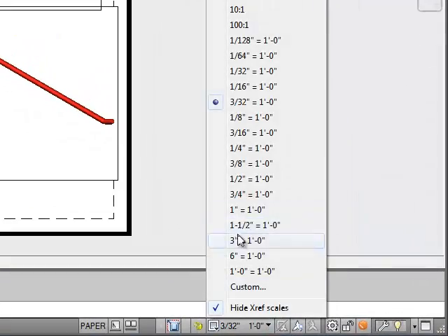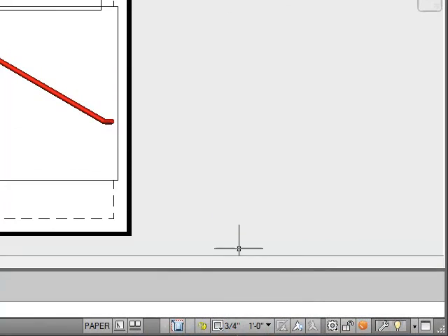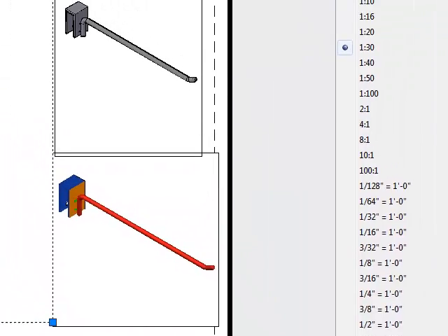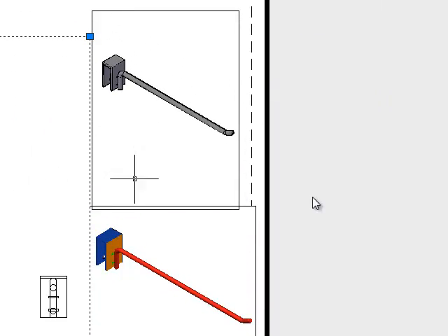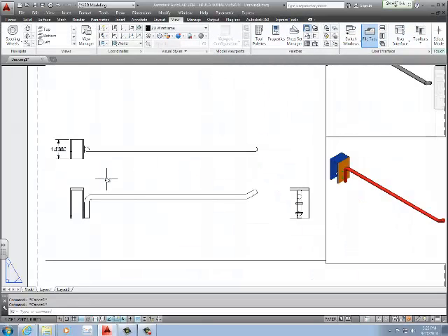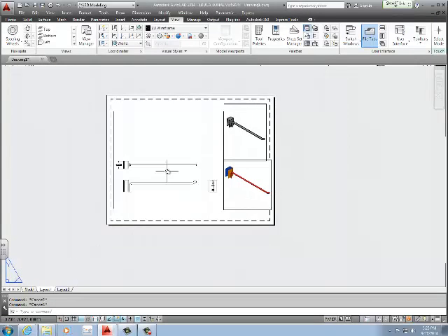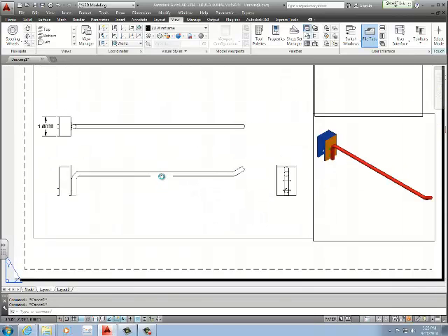Oh, wrong way. That's right. One thing to notice is that if you do not make this a polyline, meaning a single line, it will not follow through with making that sweep. So that if somebody uses a ruler to measure out anything else they may need, either use P-edit, polyline edit. For actual manufacturing, the people that will make this wire bend will need a full scale design.